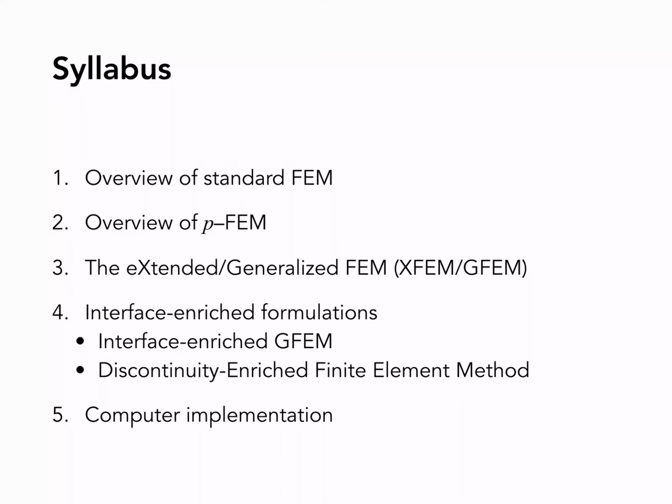And so you have many problems in engineering that have this type of description. You can think, for example, of composites, where the difference in material properties at a sharp interface gives you this behavior in the gradient, okay? And then I will also talk about something super new. This is my new work here at TU Delft. I called it the discontinuity enriched finite element method, and it's basically a new approach to handle both weak and strong discontinuities independently from the mesh.